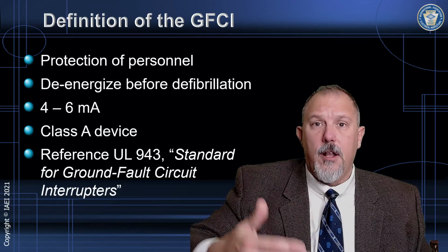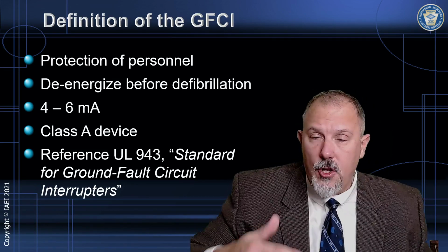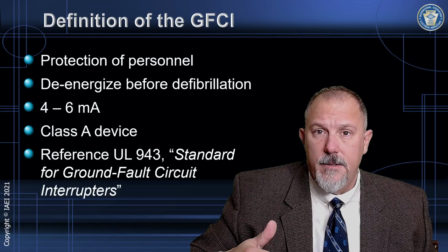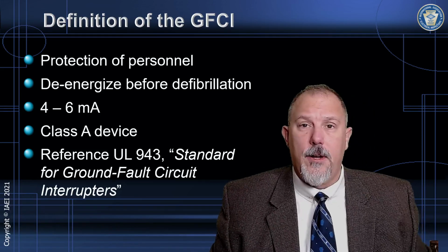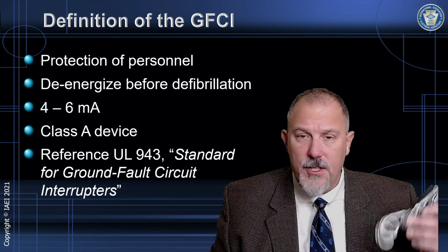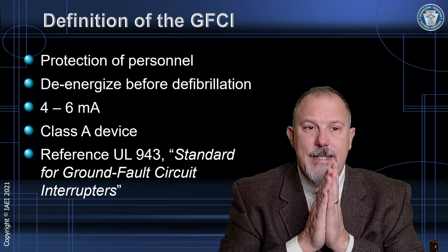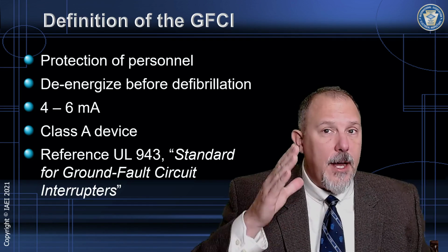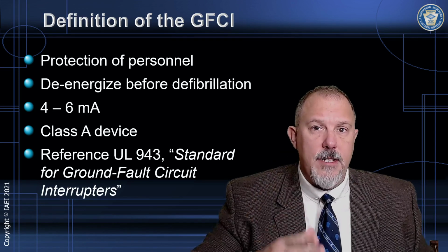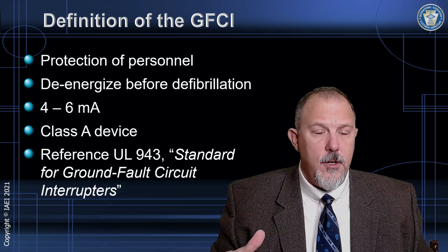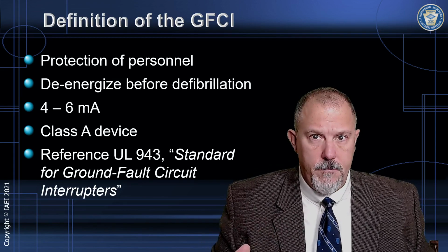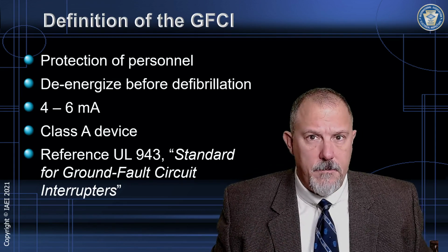There are a lot of other steps that you should take before you start to rely on the GFCI. Again, the GFCI is your last resort. We want to de-energize the circuit should a person come in contact with an energized conductor or an energized part in the power distribution system.